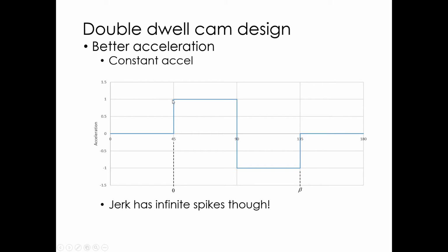Okay, so let's do a better job. So let's say we do constant acceleration. So now our acceleration is going to be no acceleration, no acceleration, bang, constant acceleration, bang, constant acceleration, and then back to 0. Acceleration is not continuous, right? So that's not going to work.